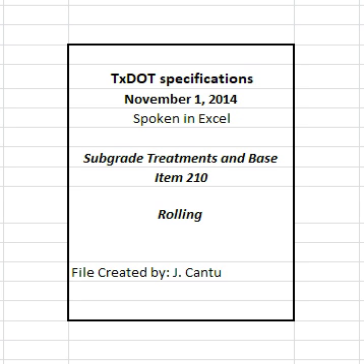2.3 Vibratory rollers. Furnish self-propelled rollers with at least one drum equipped to vibrate. Select and maintain amplitude and frequency settings per manufacturer's specifications to deliver maximum compaction without material displacement or shoving, as approved. Furnish the equipment manufacturer's specifications concerning settings and controls for amplitude and frequency.